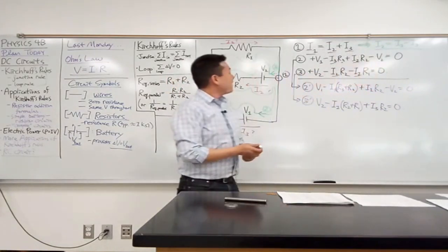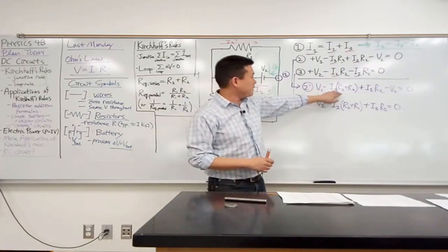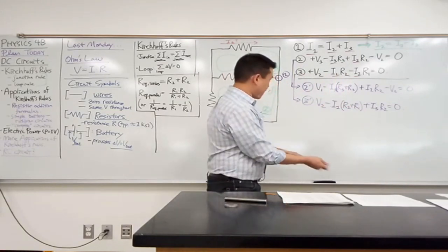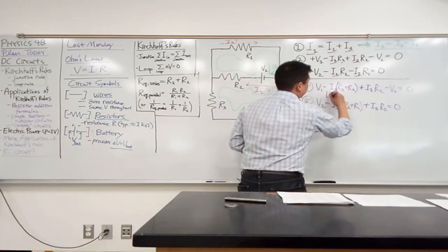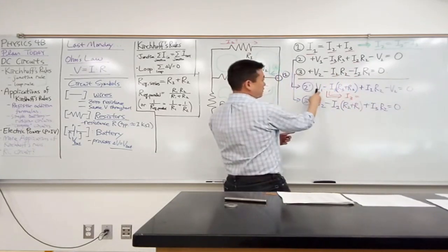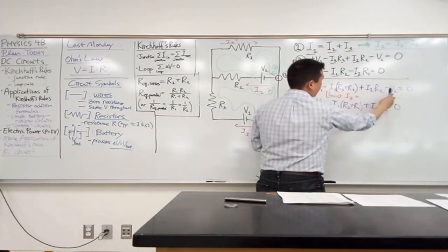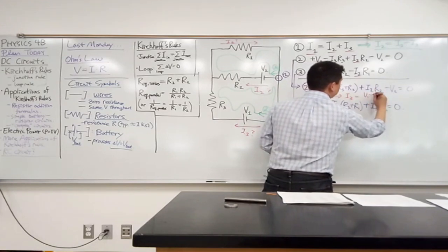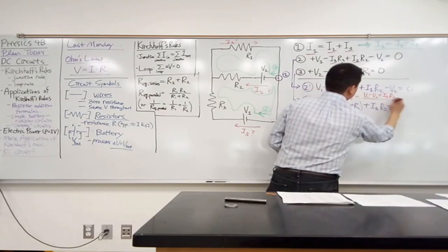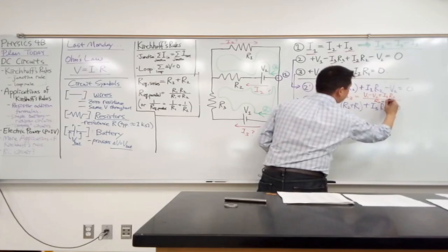All right. Okay, so I'm gonna solve this for I3. So that means I can imagine moving this to the other side and dividing by R2 plus R3. So when I do that, I'm going to get I3 is equal to everything on the left-hand side added, V1 minus V2 plus I1 R2, divided by this thing that I took over to the other side, so R2 plus R3.